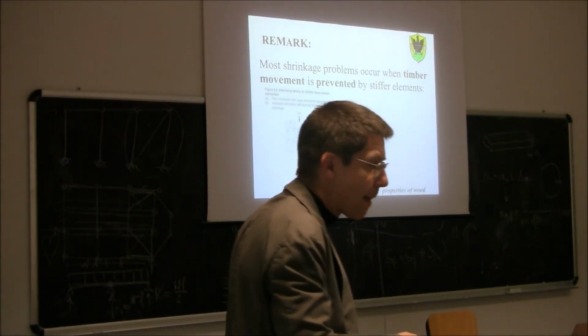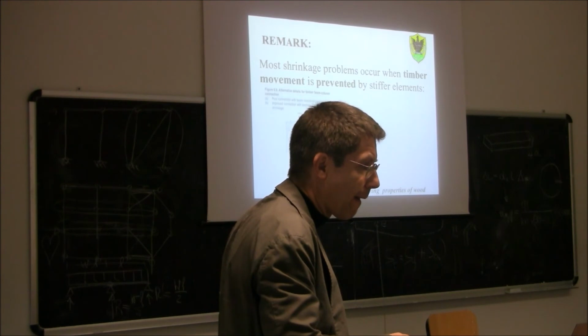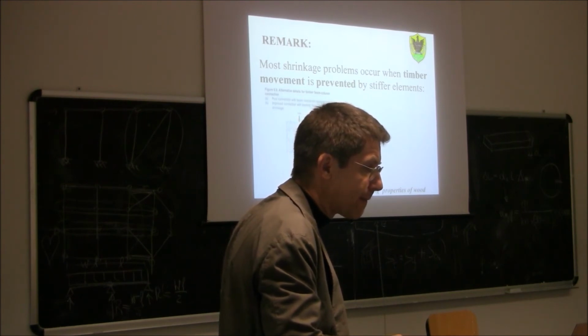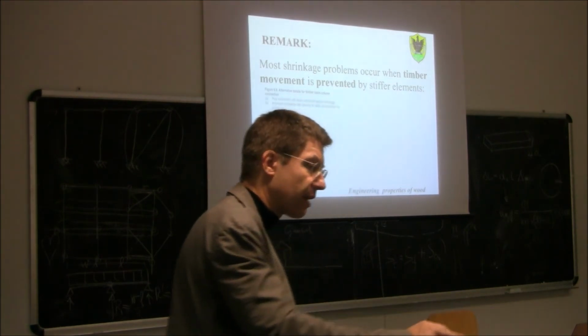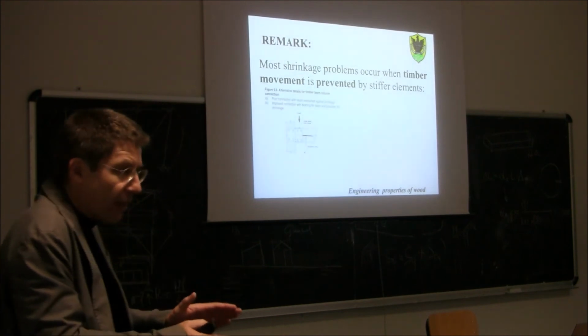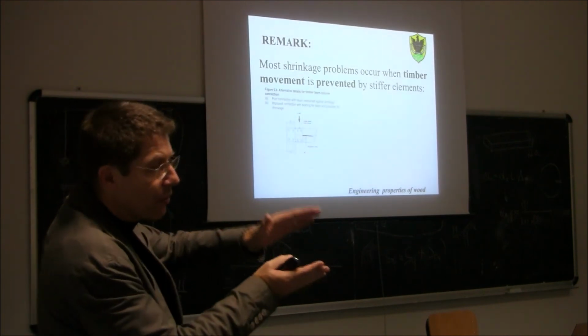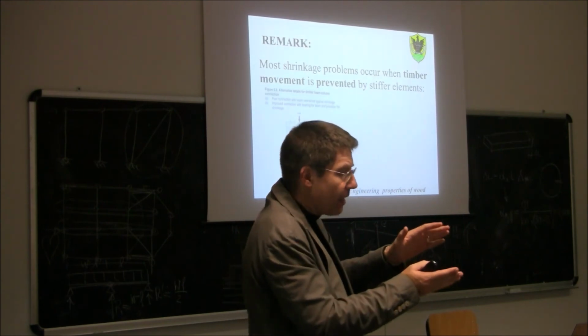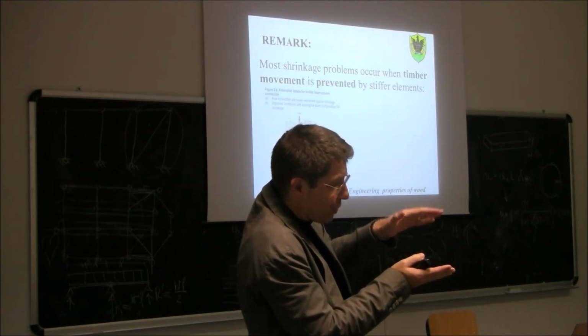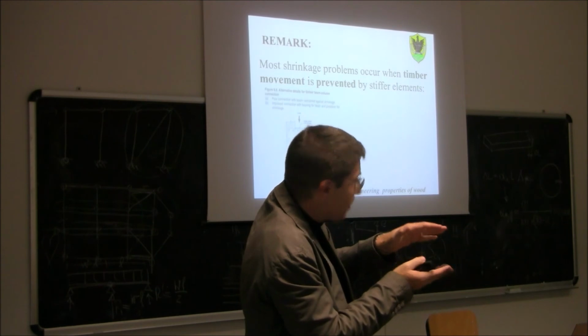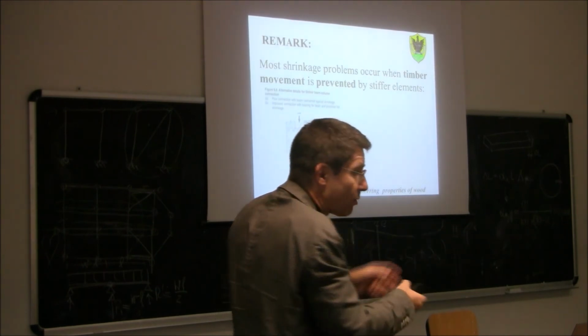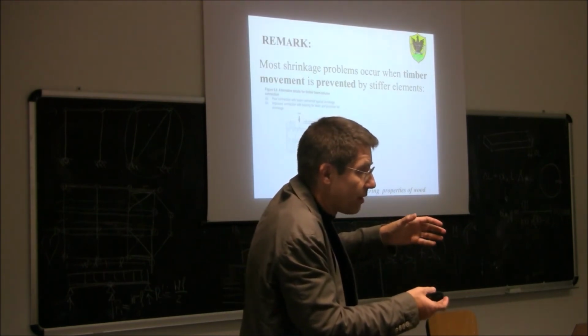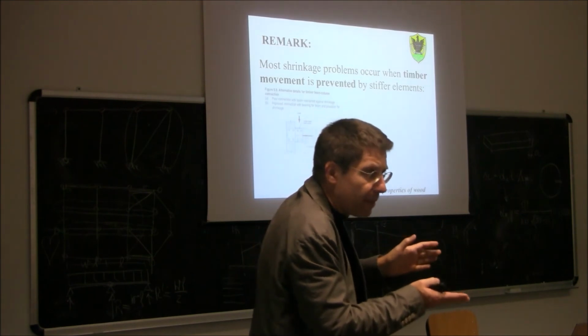No, forget about the cracking. At the beginning you don't have any crack. At the beginning you have a solid cross section, you know? Then this solid cross section would like to shrink, but it cannot because this steel plate and the bolts will keep the distance constant. So if it cannot shrink, what's going to happen?